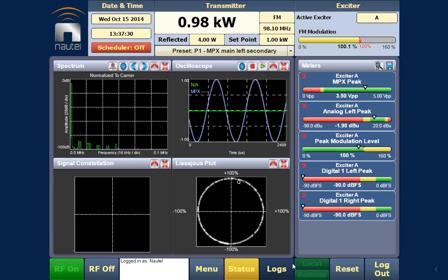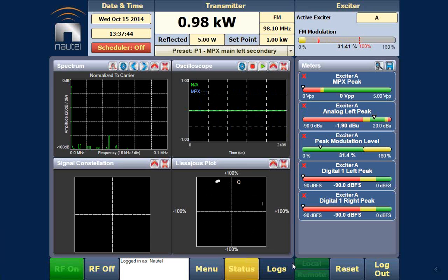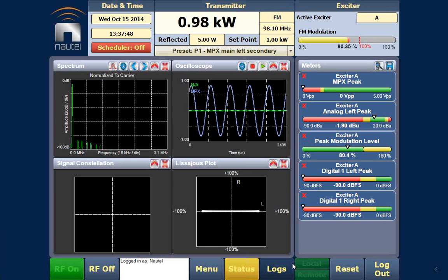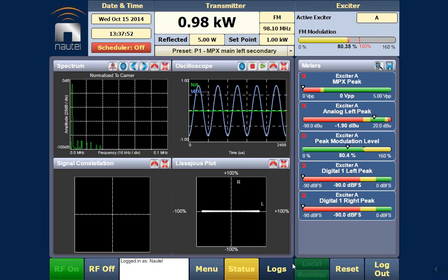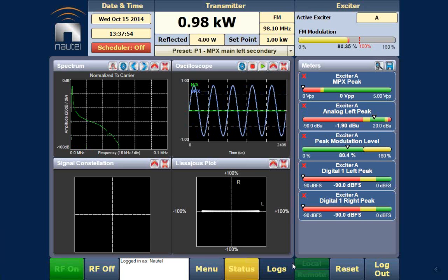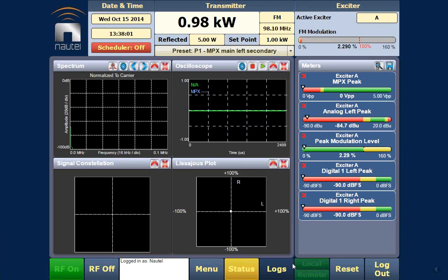Okay. So now we're going to do our little loop that we simulated. Pull both of them. We're going to pull MPX first so that we can switch over to the left. Okay. So I'll ask Leah to do that. There it goes after 5 seconds. And we're back. Now we're going to pull the left, and it should transfer after 10 seconds to preset 2. Okay, it's been pulled. At which point it's going to immediately look for MPX because that's our main source.